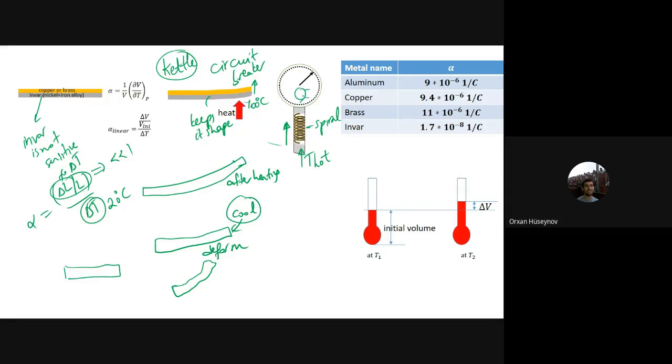And here you have the gear combination. You have the gears, and this gear combination allows us to change this linear motion into rotary motion here. You have the linear motion inside this sensor, and this gear combination allows us to convert this linear motion to rotary motion of this arm. And due to this arm, you can find the temperature of the environment.